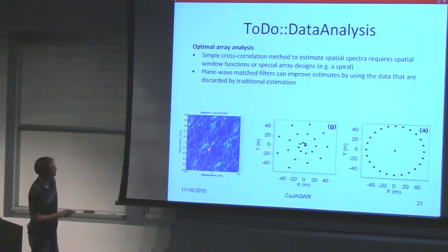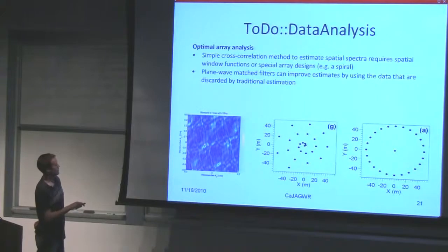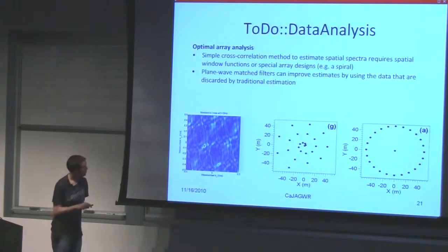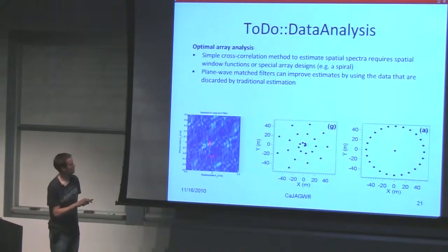What you always want to do is estimate the spatial spectrum of the displacement field. So you look at what is the amplitude at some wave numbers. This, for example, is the estimated spectrum that we got from the geophone array during the blast survey, the geoseismic survey at Livingston, but now for some seismic noise between blasts.